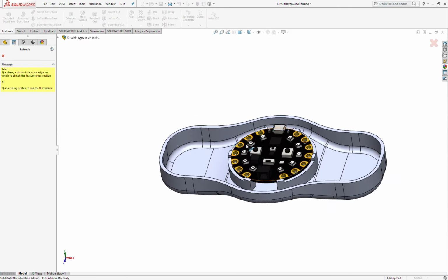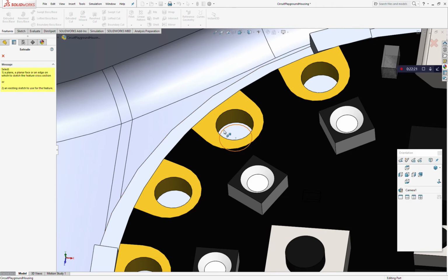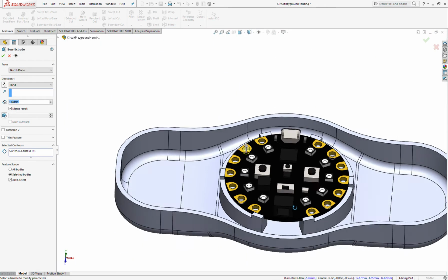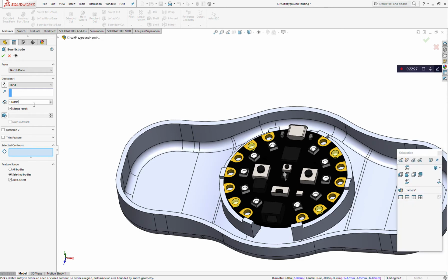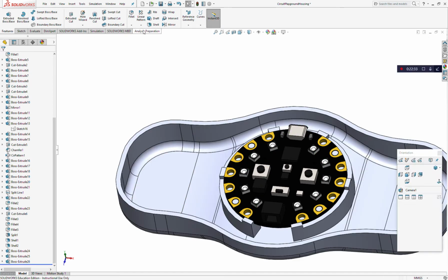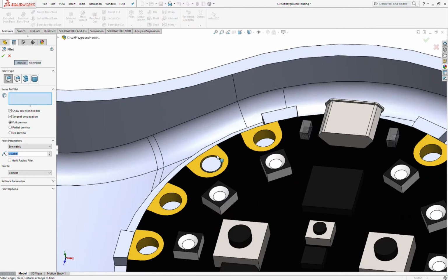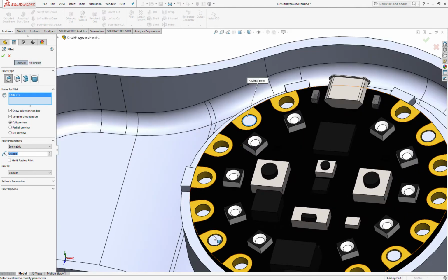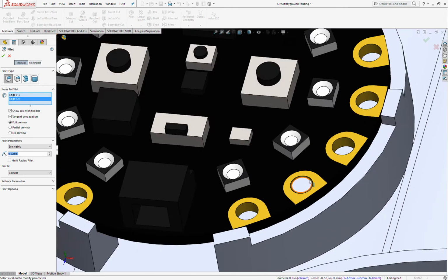Alright, now we can extrude that little guy and his buddies. And we're going to extrude those the same 1.6, making sure we're merging with the correct body. Cool. So now, just to make getting this in a little easier, I'm going to throw a very small 0.5 millimeter fillet onto these pegs.